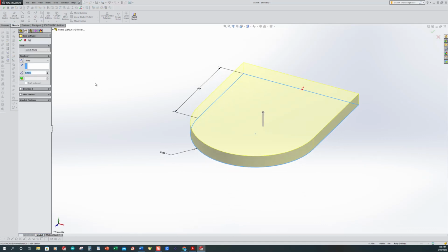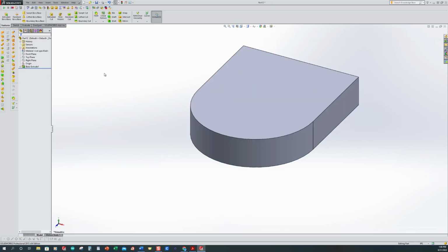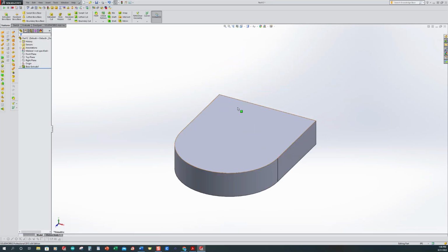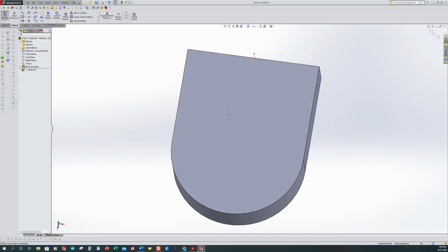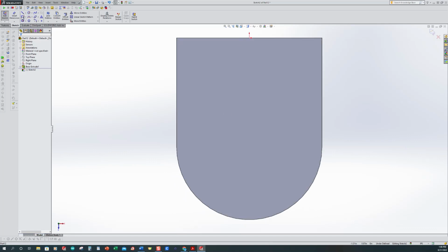And since we'd selected extruded boss before, it's going to automatically put us back into extrusions. We want to make the magnitude 0.25, so that's how thick our first level is. Next, what we want to do is put another extrusion on this top surface or top face. So pick extruded boss face, select this face. Shortcut is Control-8 if you need to.